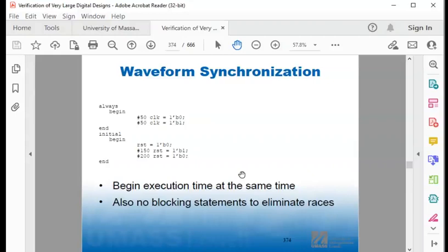It's thought of as good practice that if you have a reset, and it's not necessarily the way hardware works, you bring the system up in a non-reset state, 0, set it to reset, take it out of reset. So I know how hardware works, right? In hardware, you don't have active high resets like this. You generally have active low resets. And what you do is you hold the reset low, you power on the system, and then you let reset come up.